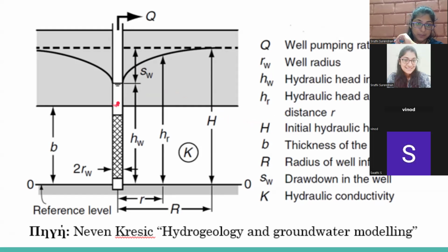That is as a result of the pressure of water, as well as the position of the water from the reference level. Here, since the reference level is starting from here, you can say that this will be the hydraulic head. Suppose the reference level is starting at a line that is way below this, you have to calculate that height also along with the pressure energy.